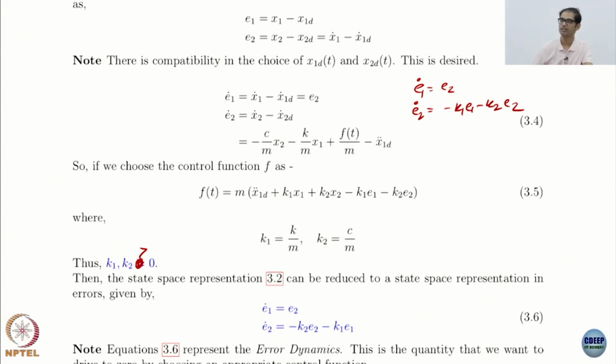So, it is like an internal model principle, basically that is the idea, it is introducing an internal model. But if you already know your feed forward term, which is this, you do not need the integral, this is enough, okay. Integral term is required if you have modeling errors and you do not know what your proper model is, then you need an integral term, otherwise you have a feed forward plus a PD, good enough, okay, great.